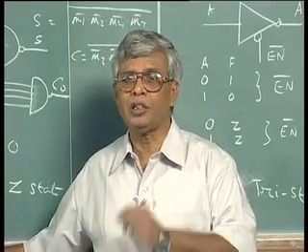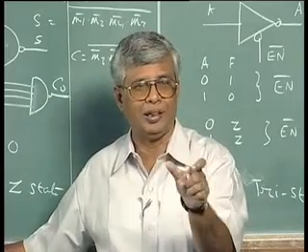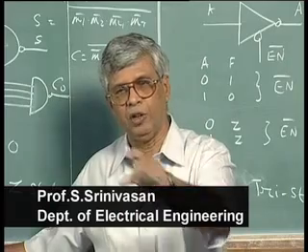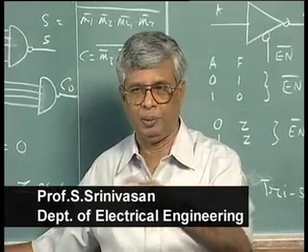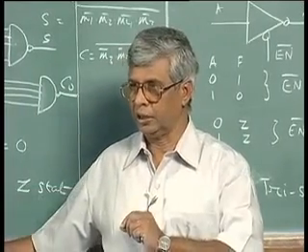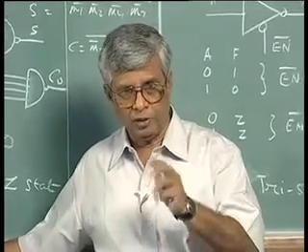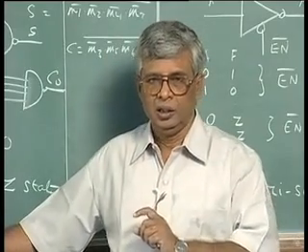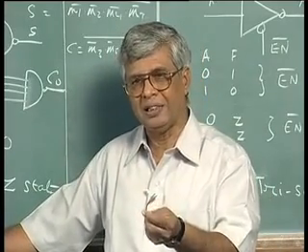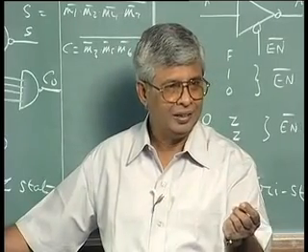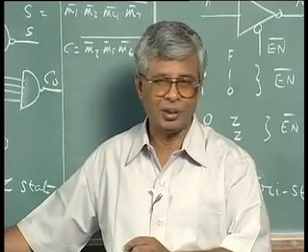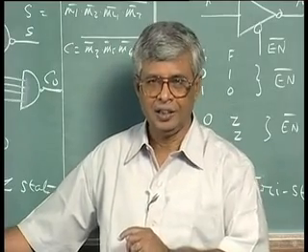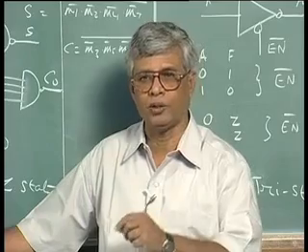So functionally, a small scale integrated circuit can do the same things, but putting them together becomes an MSI. The same way, a counter can be, a register can be an MSI. Even though a flip-flop is a small scale integrated circuit because it only has a couple of gates, at the most 4 or 5 gates, including clock, when you put flip-flops together to make a 4-bit register, a 4-bit counter, they become MSIs. So we have now used MSIs without our knowledge. 4-bit full adders we use in our design, adders, subtractors and all that type of thing. We are talking about counters and registers, shift registers. These are all MSI circuits. They are also MSI based design. Of course, you can also use them in some other ways. We will see it later on.